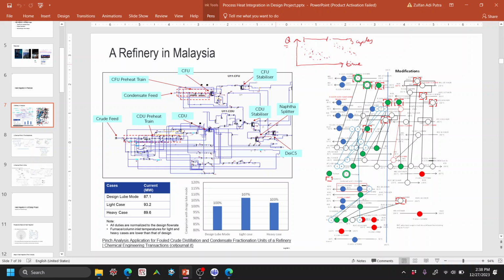And then we can see the typical performance of each of these exchangers, and we can say that if one exchanger is moving towards this area, because then the heat exchange is very low, that means probably the fouling in the exchanger is very big already. That means we need to clean this particular heat exchanger. So that's roughly how we identify the green heat exchangers.